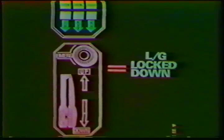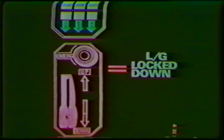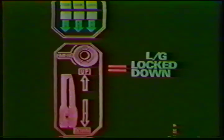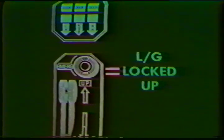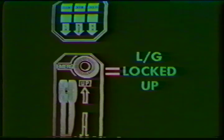When the gear handle is in the down position, the gear will be locked down with the doors closed and the green lights will be illuminated. When the gear handle is in the up position, the landing gear will be locked up with the doors closed and the lights will be extinguished.